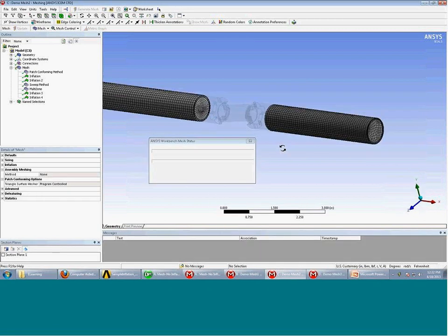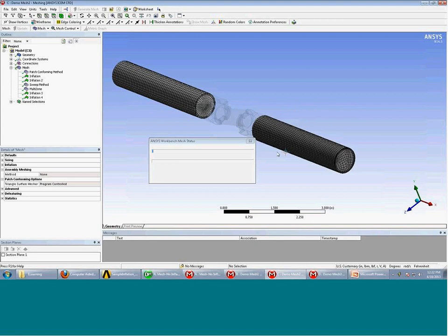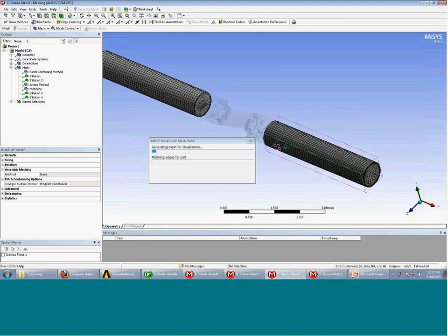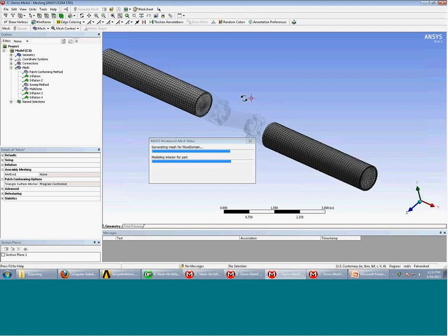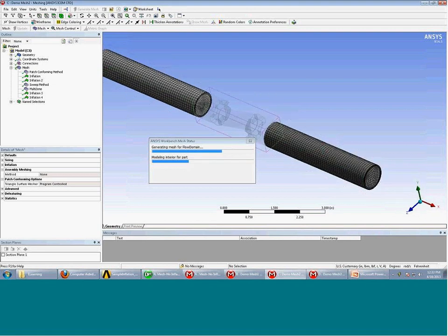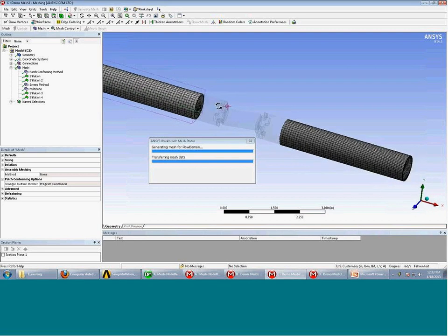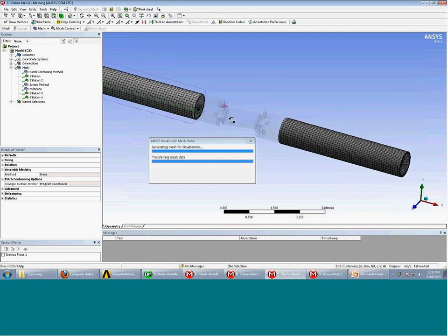So one thing to note over here is that the meshing order sometimes is also really important. It depends on how you generate mesh in a certain order. This has been demoed in the past webinar. In this case, since I'm generating the first two, the hex meshes, the faces have chord mesh, and that's what is borrowed when it's generating the mid-body mesh.